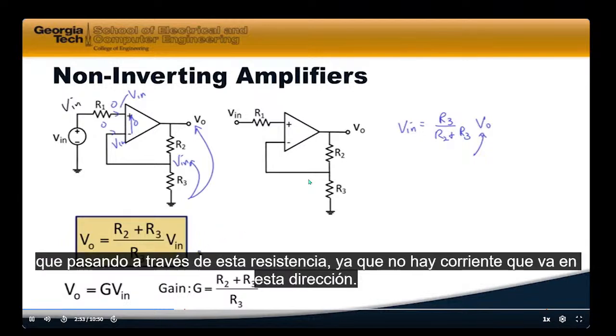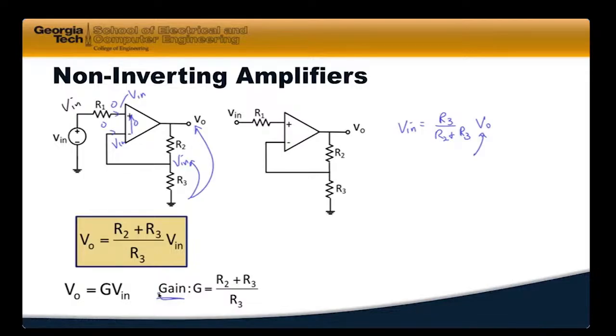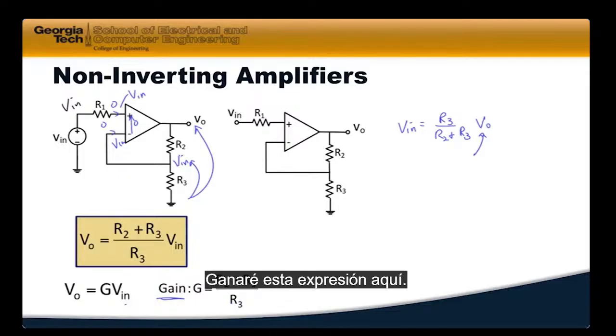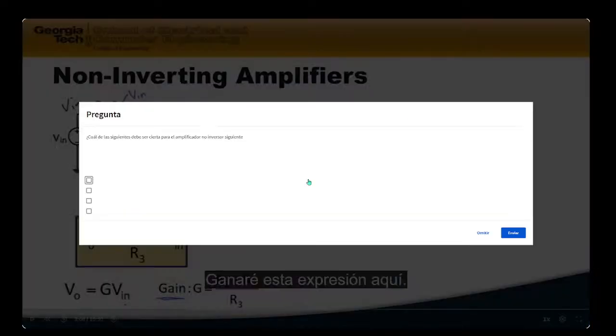Now I've defined a couple of things here. Gain is an important concept. It's the gain of the circuit. It's a relationship between the input voltage and the output voltage. In this particular case, the gain is R2 plus R3 over R3.